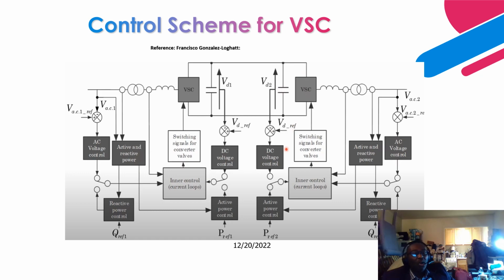So this is your direct axis voltage and quadrature axis voltage, calculated from the error in the quadrature axis current and the direct axis current. It provides the firing signal to the converter as well, also based on the measured DC voltage that comes in.